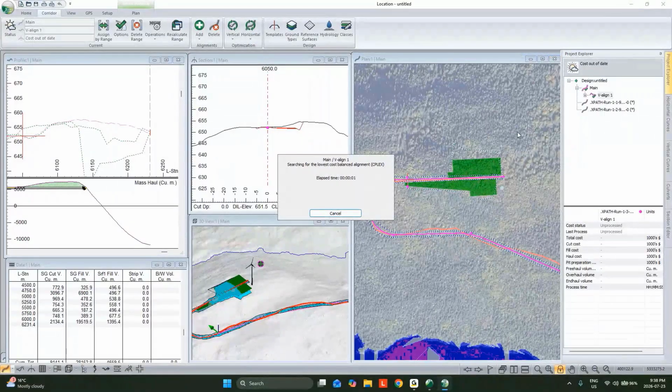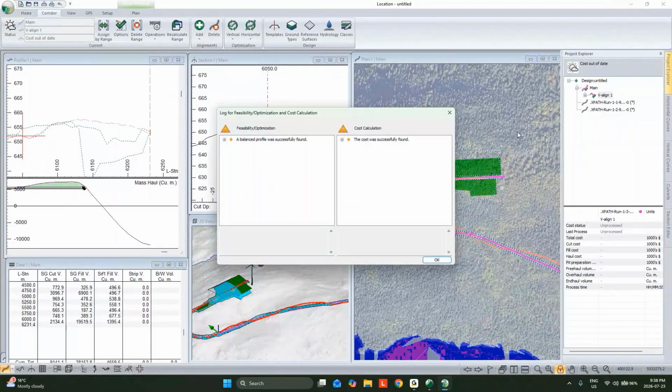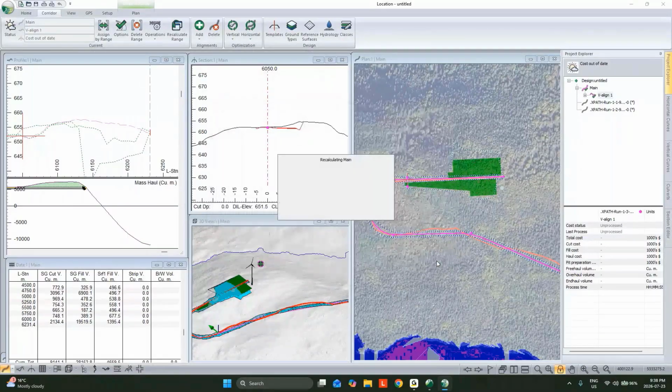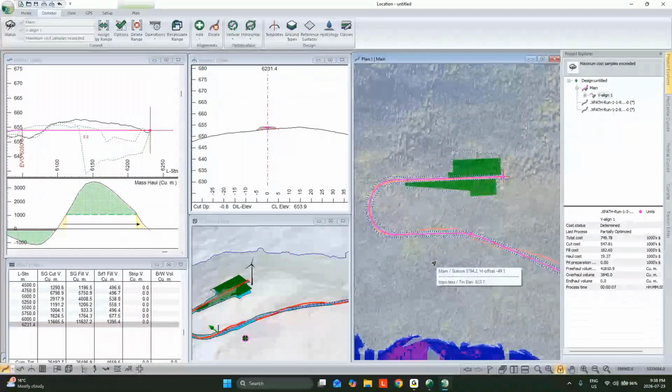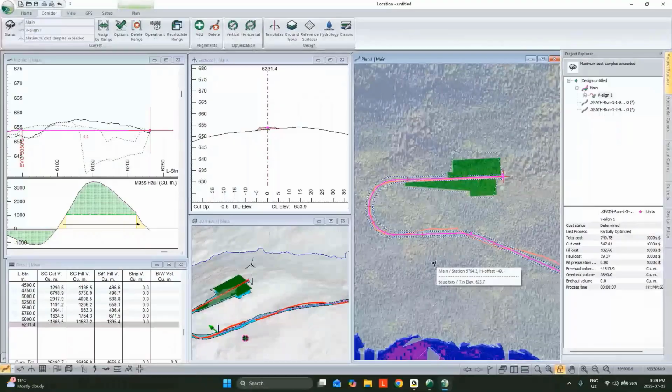Quick question, this one should be easy. Can you use shapefiles or points for the wind turbine locations instead of manually inserting them? Yep. So the example that we had here, that WTG file that I brought in, was from a shapefile. So yes, shapefile, absolutely, and we did it in this case. But other common formats, you may have them in, say, a DWG, DXF, DGN, KML even. Kind of all the common vector formats, we have that covered. So you don't have to draw them in or anything like that. You can work with the data that you already have.